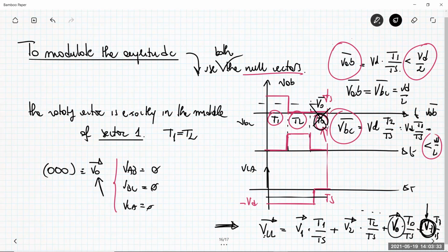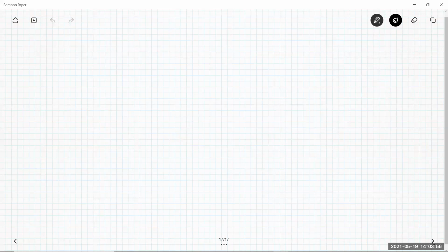So the total harmonic distortion you can get is a little bit lower for certain specific cases with respect to that of the standard classical sinusoidal linear pulse width modulator. I hope that this answers your question. So I just want to formalize a little bit this discussion. Okay, thank you.